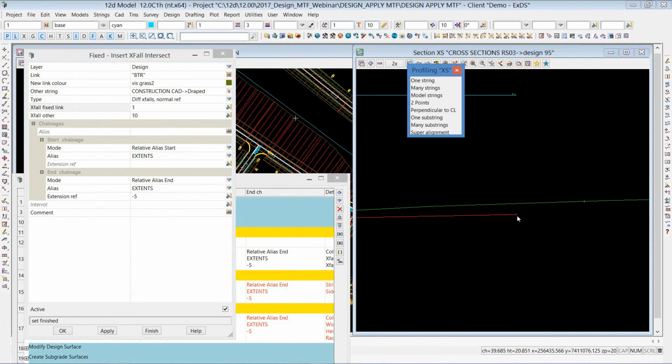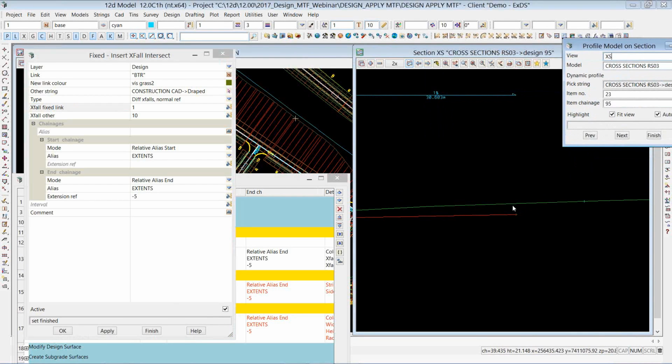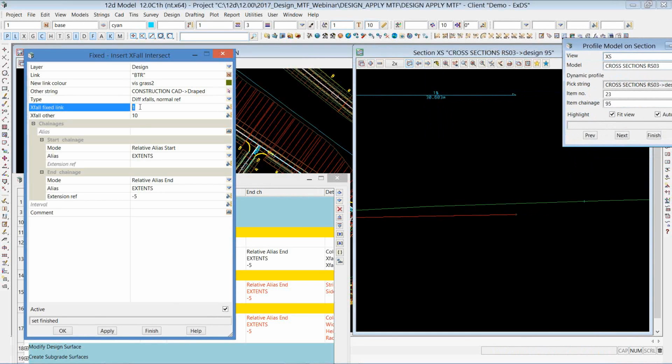It's used quite a bit also by the highway designers, where you might be doing a dual carriageway, northbound and southbound carriageway, and those carriageways would be independent horizontally and vertically, and they're trying to find the depressed median. That's another case where they can actually put the 2 slopes in and get 12D to calculate off the other carriageway where the depressed median would be calculated to, or where the position could be correct.